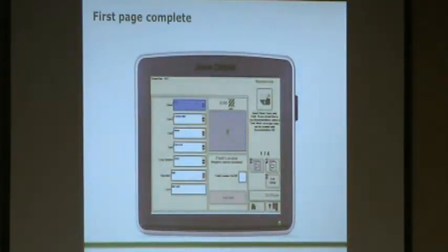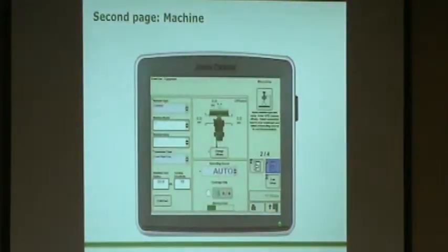And then if you have boundaries loaded into your monitor, you can also click on field locator. Just put a check mark in that box right there, and like it says, it will locate your field if you have boundaries loaded into your display. Go ahead and click the next button, and it'll bring you to your equipment. Okay, it already knows that it's hooked up to a combine, so you put machine model, machine name in there, and then you want to change the offsets.